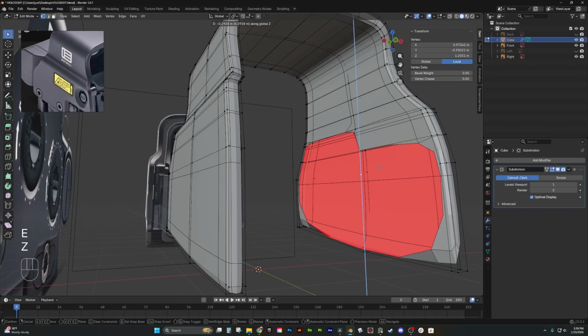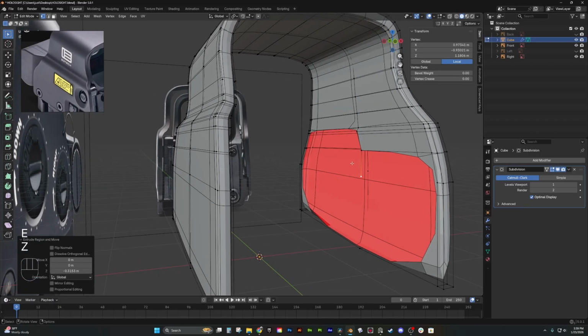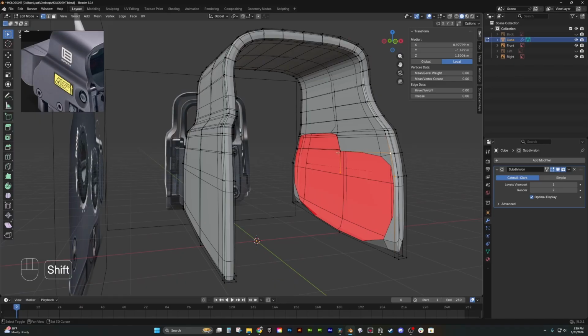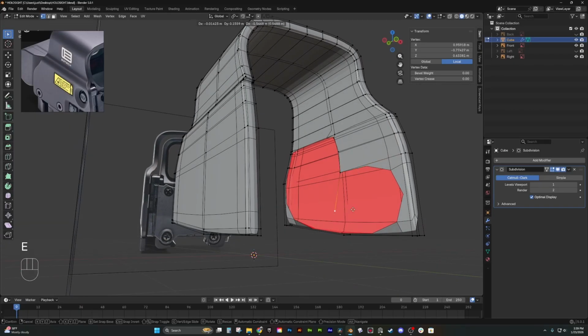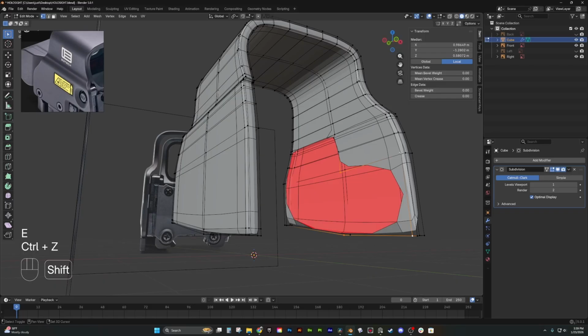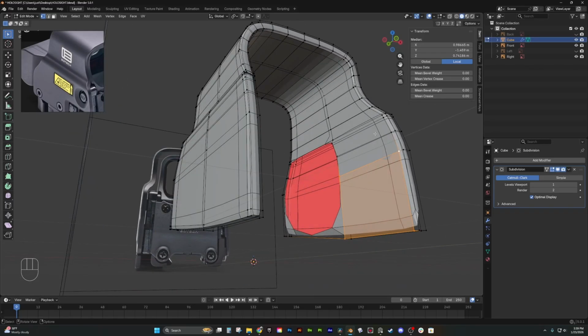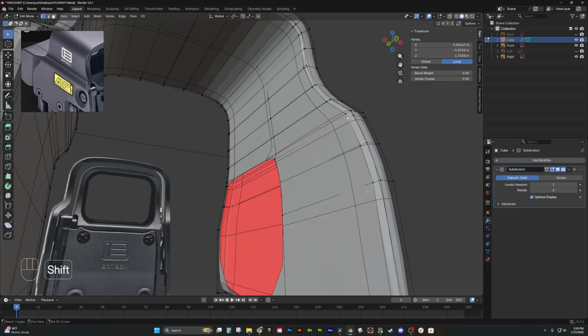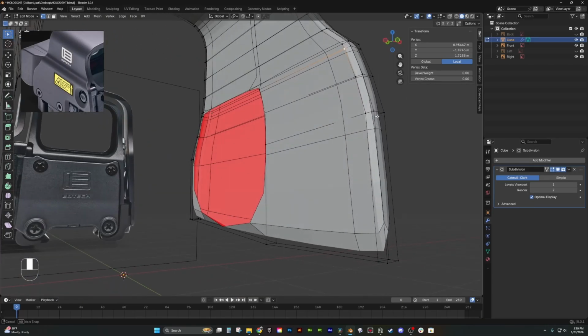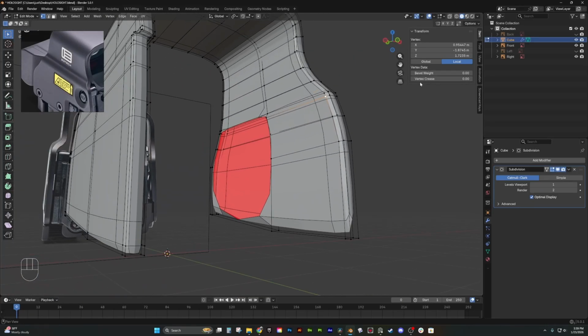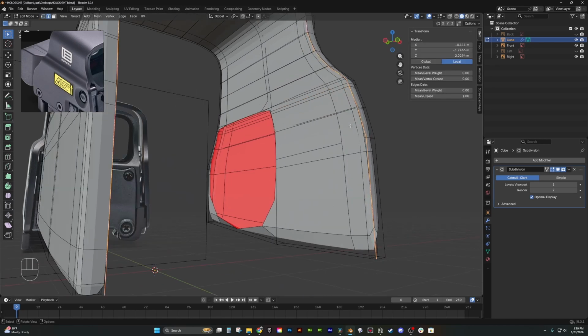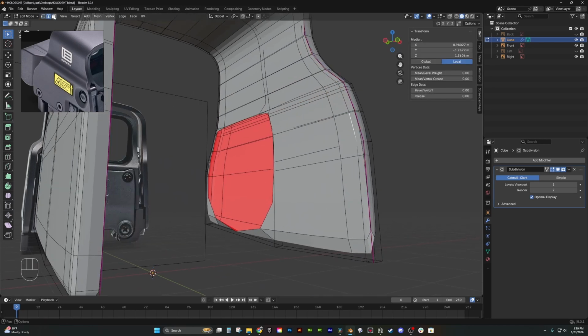But because it's a little bit of a hacky process, you want to make sure you extrude the right edge first, then grab 4 little vertices, and then you want to make sure you're not overdoing these control loops. So in a situation where I'm building faces like this, having these control loops here at the side just makes my life a lot harder. And that is a situation where I'd prefer definitely to just crease these edges to know what I'm looking at, and I don't have to add a ton of different faces one by one.